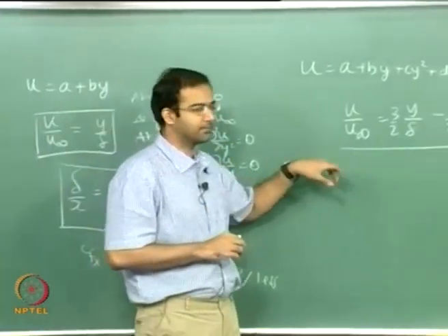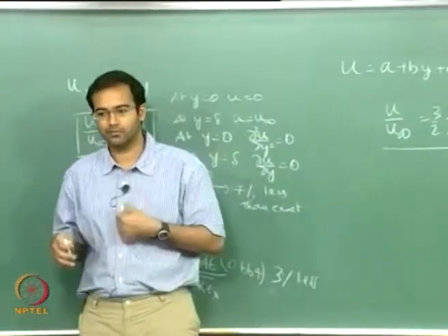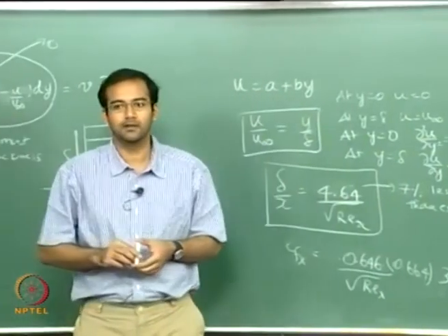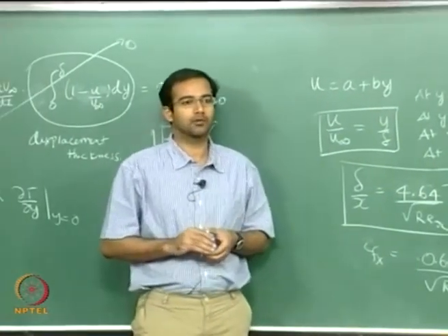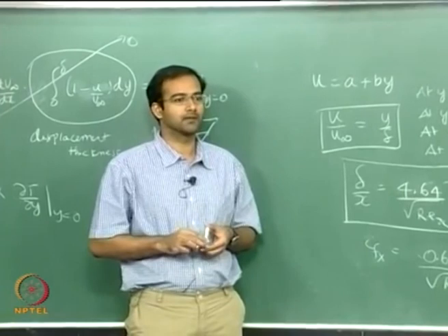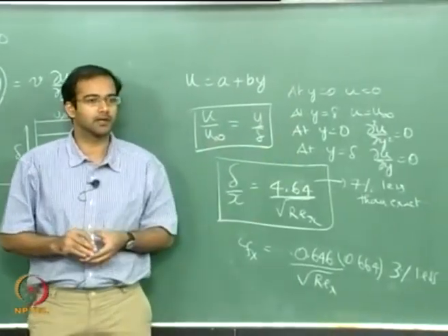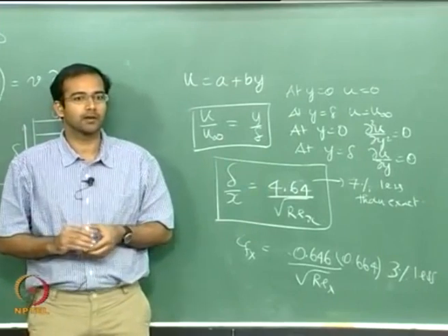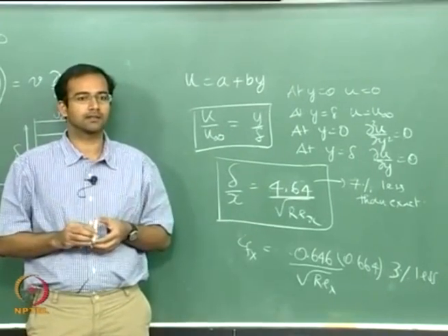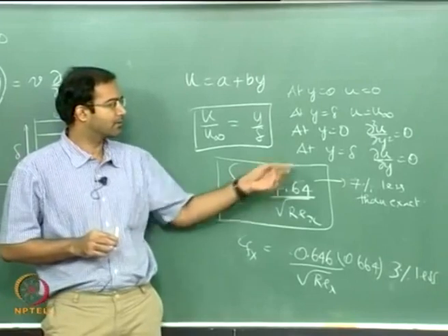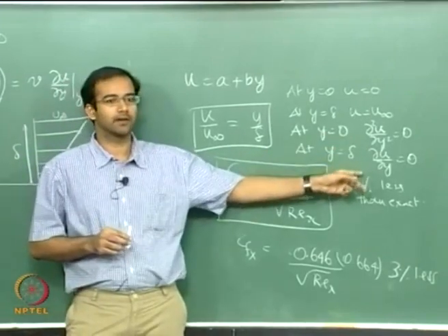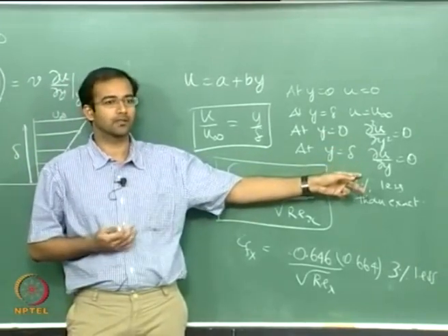Now the question you may ask is whether, if you go to a 4th order or 5th order polynomial, we can get a closer solution. It need not be. These are the four most important boundary conditions to be satisfied, and if you are introducing additional constants in the polynomial, you have to introduce higher order derivatives to be 0. Nothing more than that.